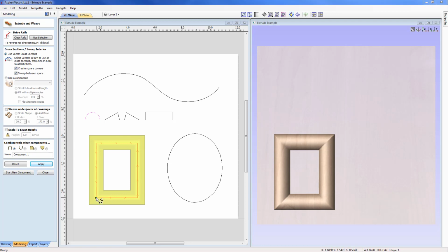So what I'm going to do now is just click in my lower left hand corner there, which shows the mapping of the circular cross section to that point, and we can see that the red point matches the red point on the cross section. And I'm going to right mouse click now over that cross section, say add to all rail nodes. I can do this manually, but if you've got many nodes you may wish to do it by just using add all rail nodes from one.